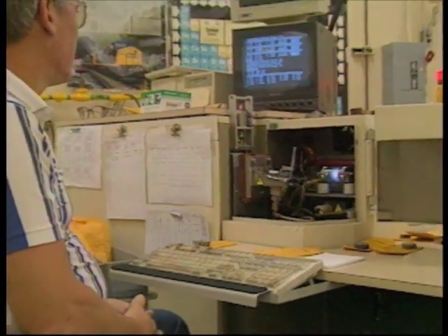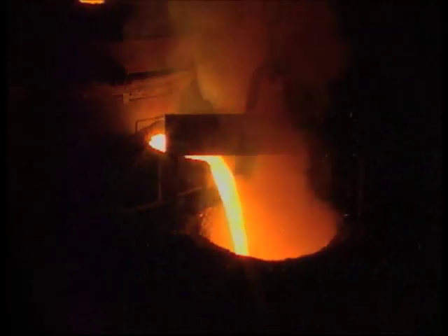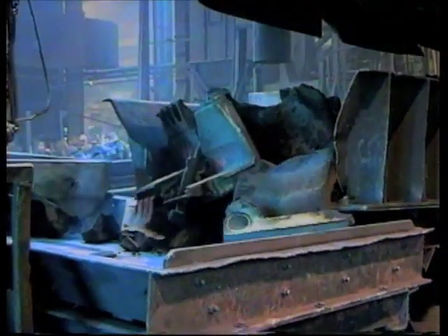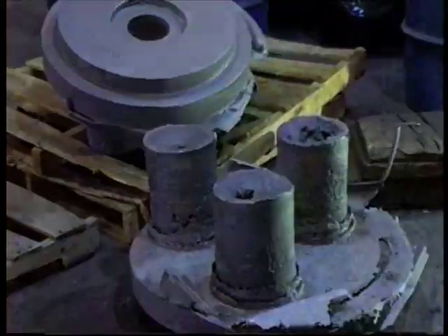Once the alloy adjustment is completed, the liquid steel that is in the furnace is tapped into a ladle that is used to pour the actual castings. The steel is poured from the ladle into the mold. After the pouring of steel into the molds, the castings are allowed to solidify and cool. The shakedown operation separates the steel casting from the mold and coarse sand. Once the casting is removed from the mold, it is ready for finishing and heat treatment.